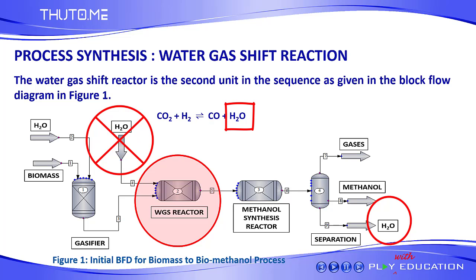I'm not saying it has to happen after methanol synthesis. I'm saying it has to happen somewhere downstream. You may opt to remove it here, you may opt to remove it here. Somewhere downstream, you're going to have to remove that water. But as we continue to build this flowsheet, you will see that we will have to assess those decisions as we carry on.